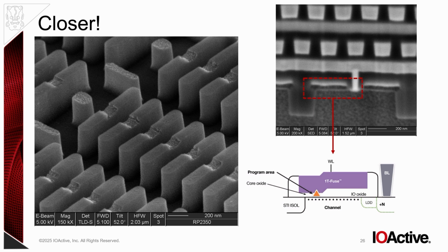Anything in the trenches is not important, it's not functional. The trenches are for isolation between transistors, to reduce the amount of crosstalk between transistors. They fill that with insulator material just to isolate them from each other.